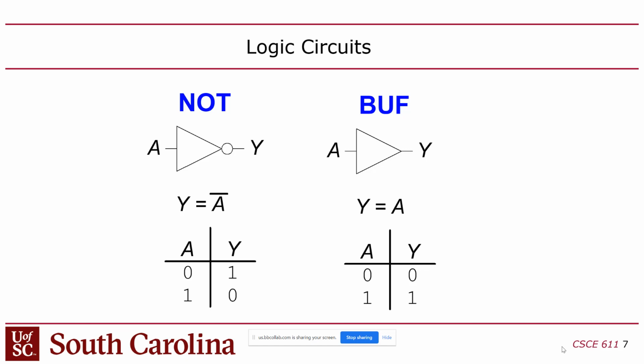Hardware is inherently concurrent. You've got these wires, and if you have an input and an output of a gate, anytime the input changes, the output is going to be updated as soon as the electrical signals propagate through the gate, right? Which basically involves charging or discharging a capacitor ultimately. And every gate is concurrent. Generally, logic circuits on a chip are all operating concurrently. There's no order there, right?